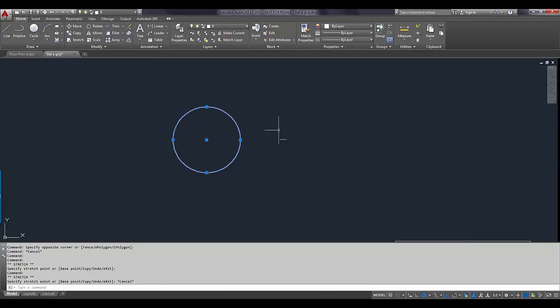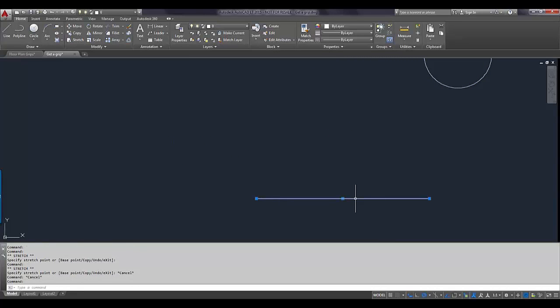I personally do not use dynamic input too much. But this is a case where I like using it because, and we're going to backtrack to the line, if I select the line now and I hover over this line object, notice because I have dynamic input on, it is giving me the length as well as the angle of that line.